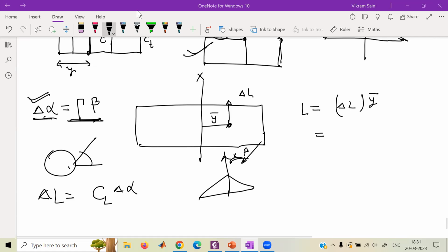What else do I have to write to compute the lift? It will be CL alpha, not CL. Then there will be Q infinity, the dynamic pressure, and the wing area. That's how you compute the change in lift.